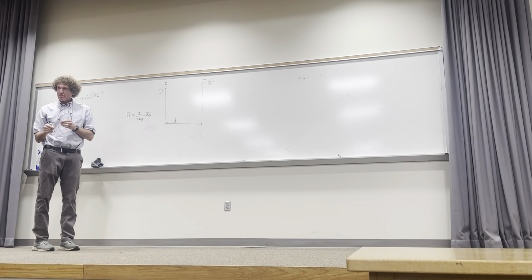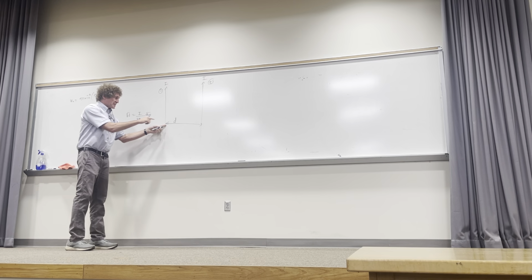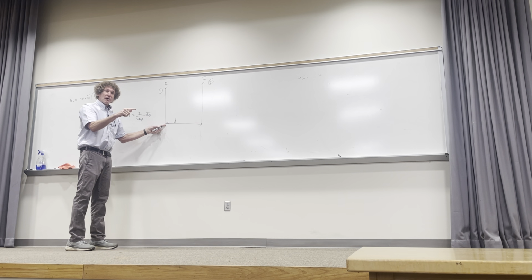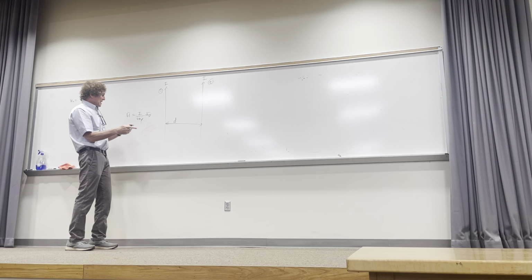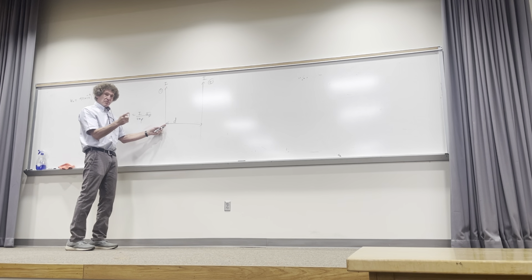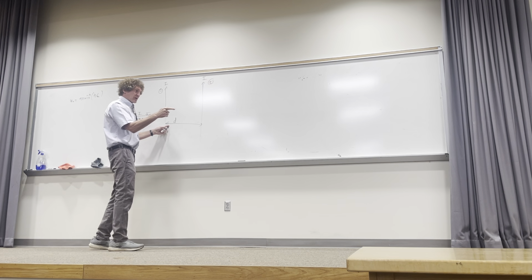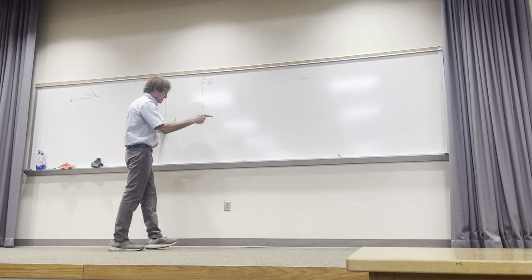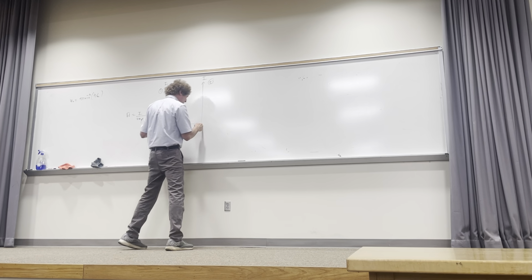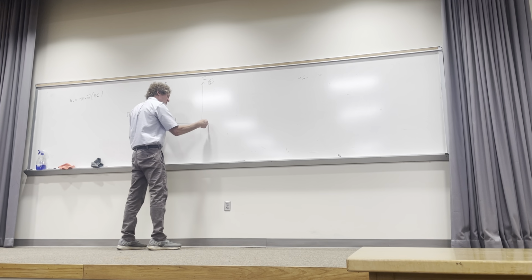Do you all follow me on that? So if I come a distance rho out from the board, I'll get a magnetic field, with magnitude I over 2 pi rho, or the distance at this point. It'll be circulating this way. Do y'all follow me? Now, as I move around, my index finger is showing you the direction of the H field. The H field at this point, in this plane where this current is, would be into the board.